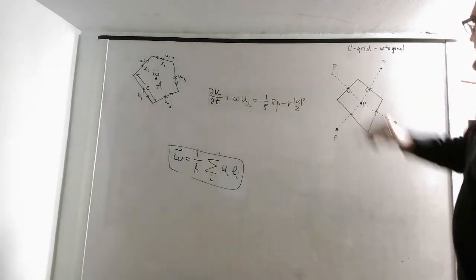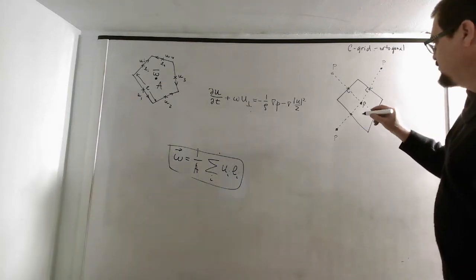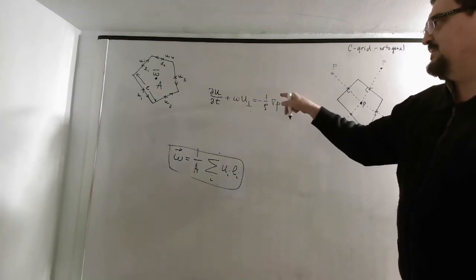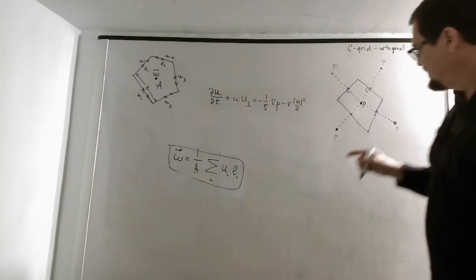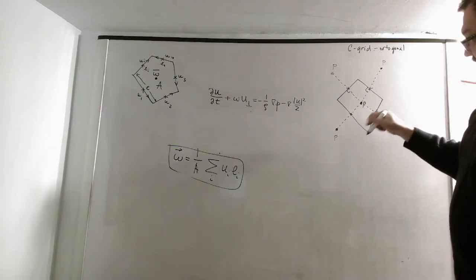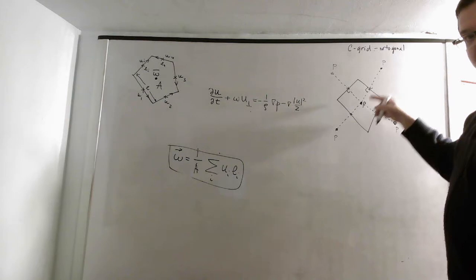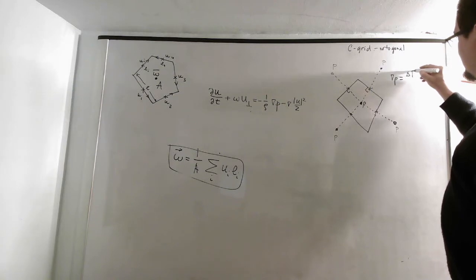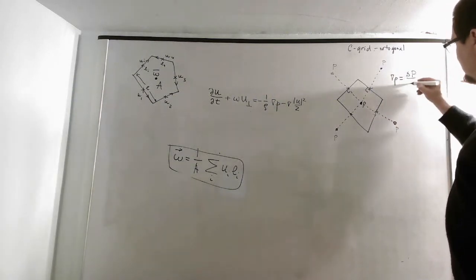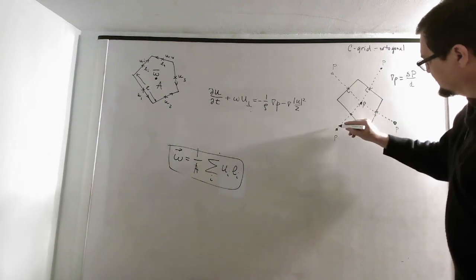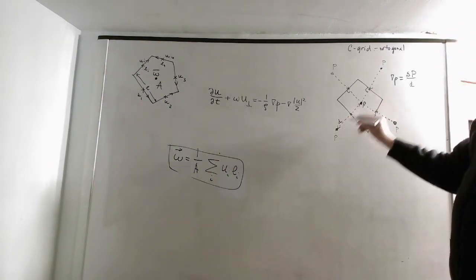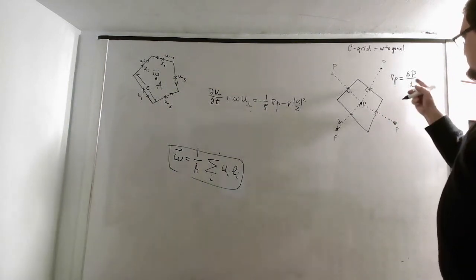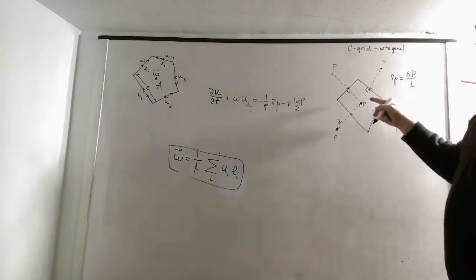of the other grid. So now we define our U's. You see, on the right hand side there is the gradient of P, so U should be in the direction of the gradient. And what's the direction of the gradient? Easy to compute here. If you have 2 points, it's along this line. So the gradient of P is basically this delta P divided by this distance D. So this distance is D. Now, instead of computing this complex thing again, we just directly compute the gradient as delta P over this distance.